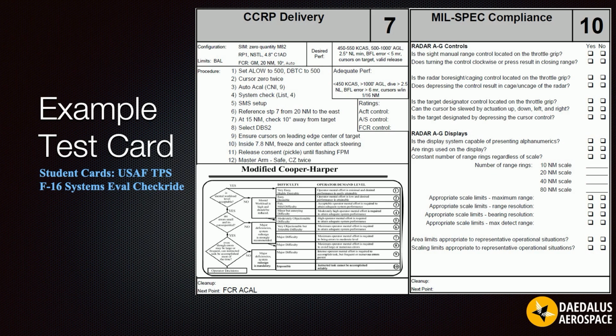The point of the check ride was to build and execute test cards that collected high-quality data to meet certain requirements of a test plan that was provided as part of the check ride assignment. Every student test pilot made and flew their own cards for this check ride. I sized my cards to fit my kneeboard in order to provide detailed guidance for flight test execution while also leaving me room for notes and data collection.